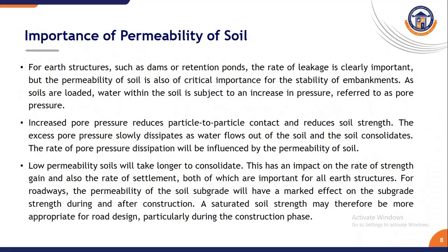Next topic is importance of permeability of soil. Here, permeability affects the consolidation and pore pressure dissipation. Low permeability soil consolidates slowly, leading to delayed settlement. In highways, poor drainage due to low permeability weakens the subgrade.